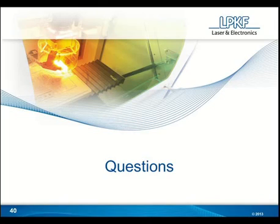For LPKF, we have a couple of different options for you at least. If you work with a lot of very thin materials like polyimide or PET sheets, we have systems that come with a vacuum table. The vacuum table will hold the material down while cutting, and it will hold it perfectly flat, and you don't need anything additional to keep the material down.